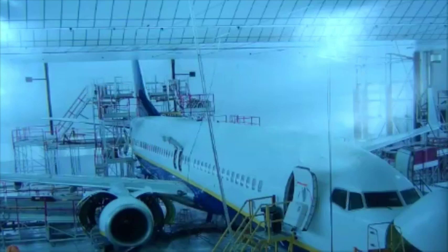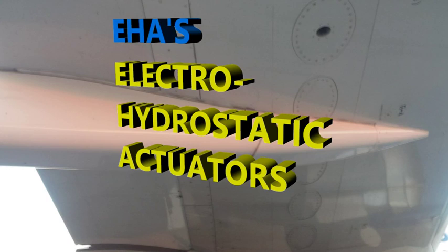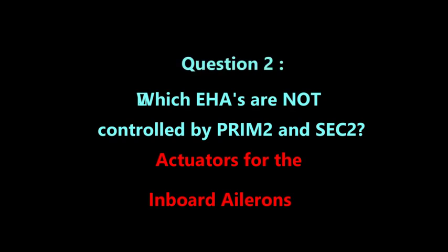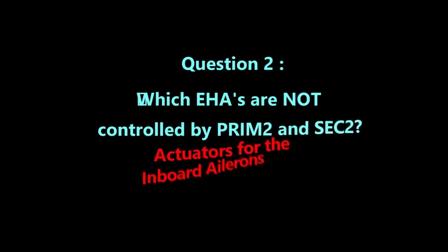All right. Now let's talk a little bit about the electric hydrostatic actuators. Anything that's electrical. These become active when there's a hydraulic or an electric failure. Okay. And the power is supplied by the computers that are sending the signals to the module. Okay, we're talking about the remote control circuit breaker that goes to the EHAs and your EBHAs, your electronic backup hydraulic actuator. Power is also supplied through the power lines that go directly from the computers, and they're supplying a 60 volt DC. All right, so you know about that.